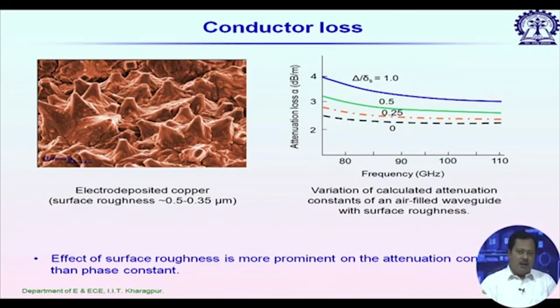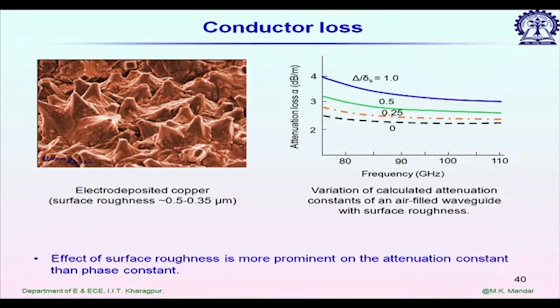Another important observation: when we order our substrate to design millimeter wave components, we also have to look at the surface roughness value. If the surface roughness is very high, then we will expect high conductor loss. So look at the value; it should be much smaller compared to the skin depth when you choose your substrate. Be careful about that. Another example we will take.